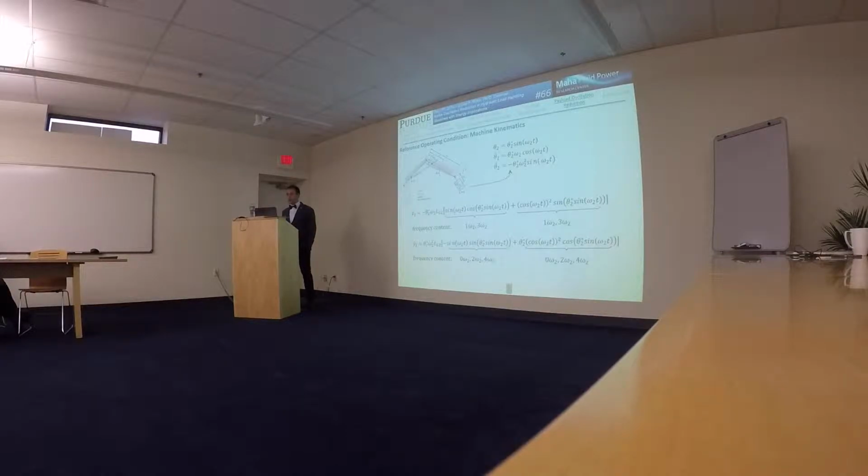And just another side note, the zero frequency does not really exist, because if you imagine a zero frequency, that would mean that we have a constant acceleration of the payload, which will lead to an indefinite drift of the payload. And this is difficult to demonstrate analytically. What I did, I used the Fourier transform of these two terms, and you can show that the sum of these two terms is 0, so that means that the constant term at 0 omega 2 does not really exist.